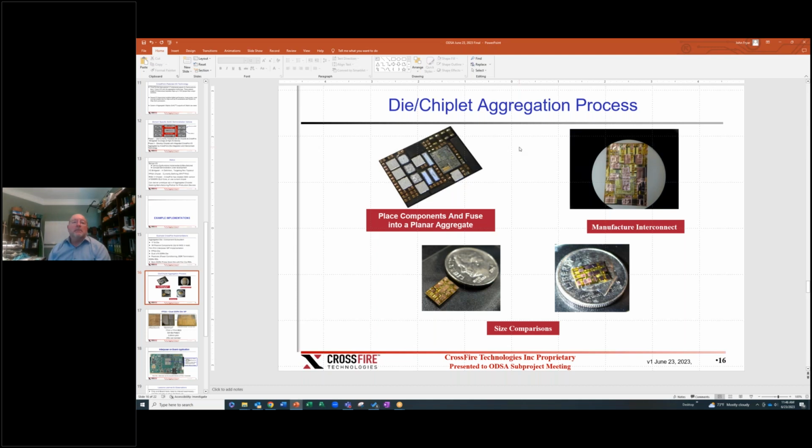I have a question. This sounds pretty similar in tendency towards fan-out packaging, and for example, from DECA, their adaptive patterning. Is that going in the same direction? Not really. What DECA does, and it's very creative, is for each individual chip and each individual wafer, they change the routing based on the placement of the parts after they've been put into their carrier array.